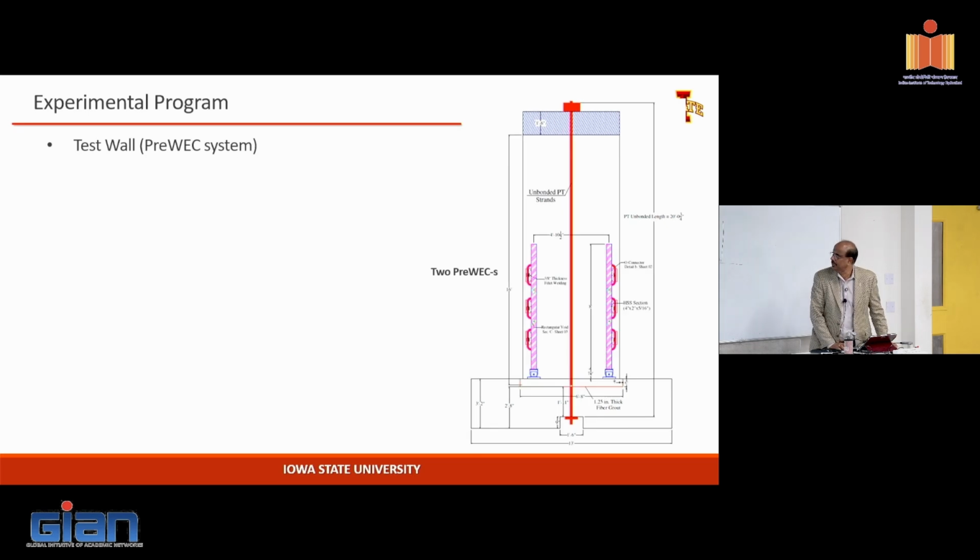Here's the other detail. The reason we partially terminated is to show that you can actually keep all of the connectors within the first floor or 2 if you wanted to. It doesn't have to be extended all the way. When you put the beams or the end columns here, the advantage is that end columns could then be connected to the perimeter frame in terms of transferring load. The gravity load can go through here without interfering with the structure.